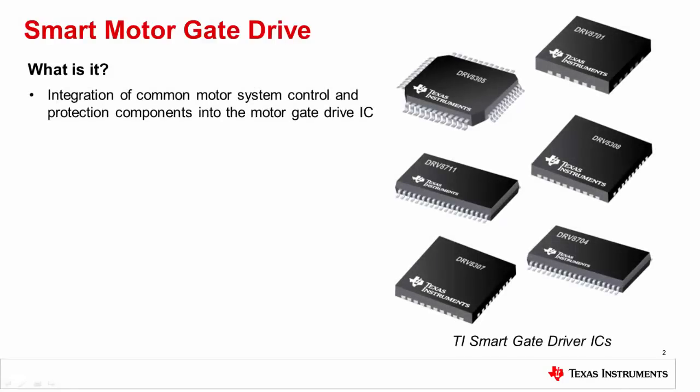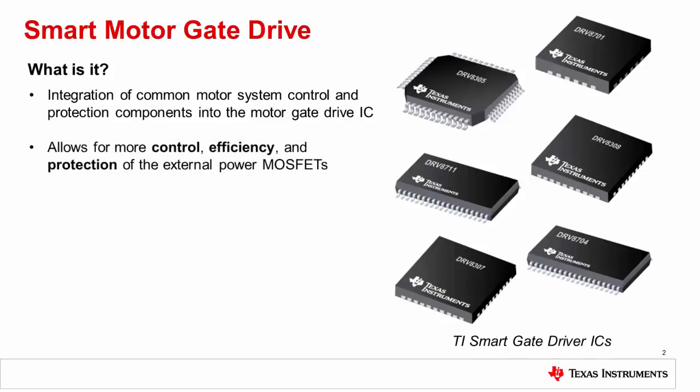Smart Motor Gate Drive is the integration of many common system components in the motor drive system into the Motor Gate Drive Integrated Circuit, or IC. This integration allows for the gate driver to provide more control of the external MOSFETs, take steps to protect the external MOSFETs, and allow for the optimal trade-offs between efficiency and robustness. In DRV8X motor gate drivers, this technology is often referred to as iDrive and T-Drive. The next few slides will explain what exactly these terms refer to.